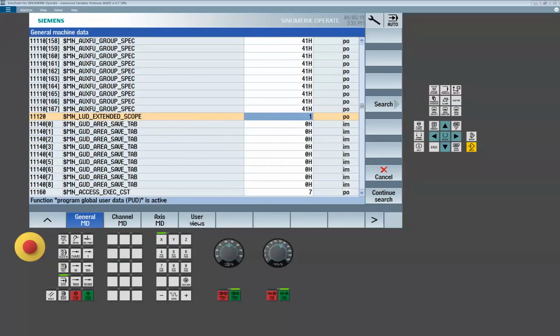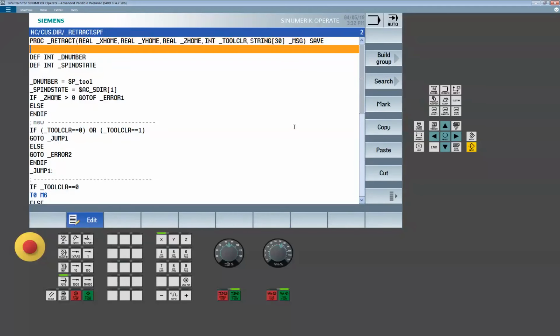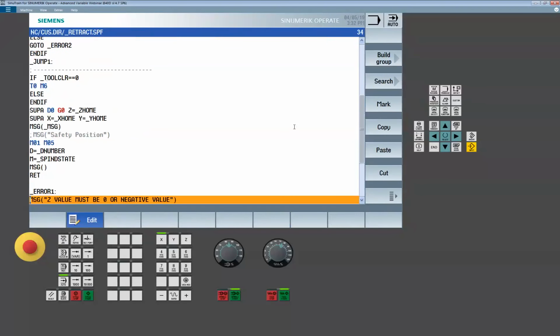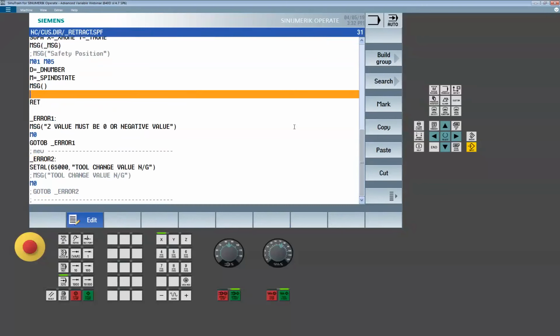Then you can put a STOPRE command in. Let me go into the routine and show you what I could do. Let's say, at the end, I don't want the system to be able to look any further than this point. I just type in a STOPRE. It's not going to do anything as far as programming is concerned, but what it does is stop the system's look ahead.